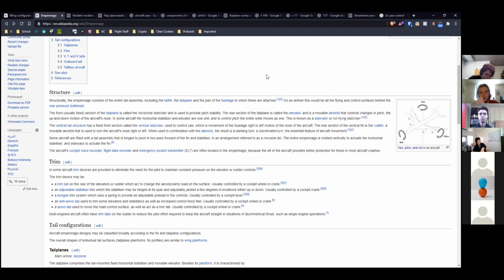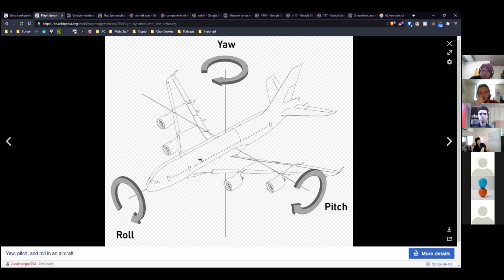You will now be out of trim because the lift generated by your wing has changed because your speed changed. The lift generated by your tail has changed because your speed changed. And until you retrim the elevator, the plane will probably start to pitch up because the moment on the wing increased more than the moment on the tail, so you now have a net upward pitch moment.